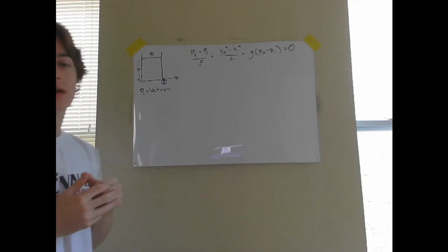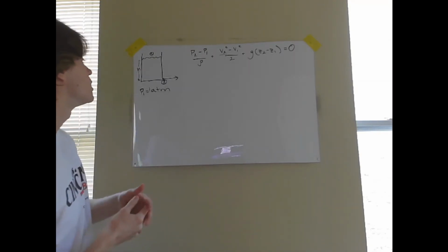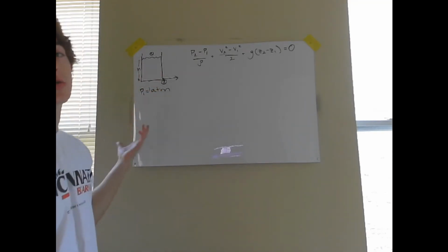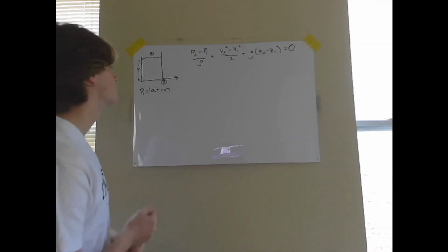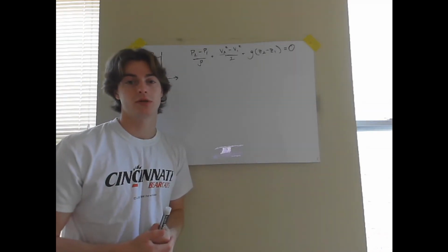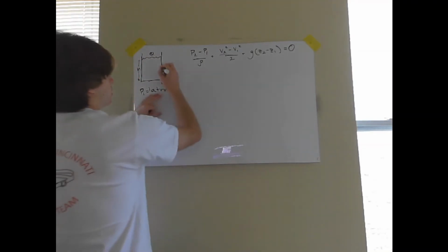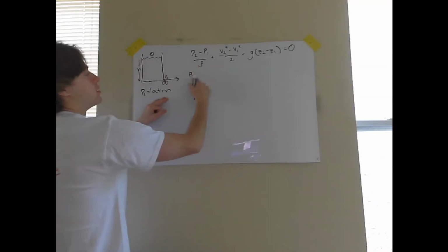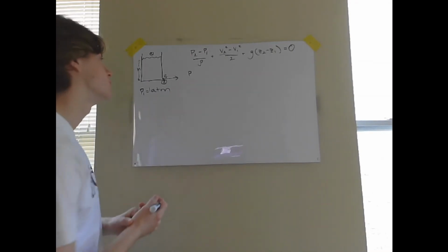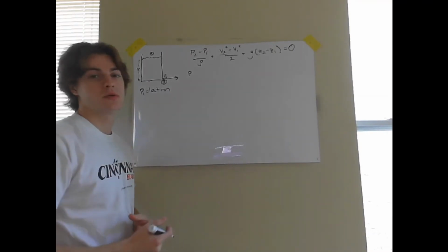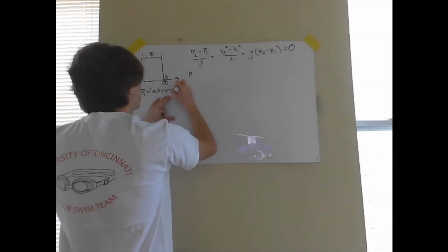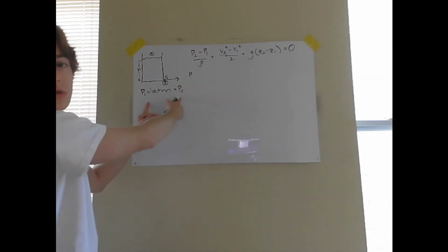Now, for the pressure at point 2, one way to think about it is we have a sudden expansion. And so the liquid rushing out of the tank goes from a very small cross-sectional area to basically a large one outside of the tank. And so when there's a sudden expansion, there's no time for pressure to recover. And so the pressure at this point, P2, is going to be equal to the pressure out here outside of the tank. And so again, since we're back out of the tank into the atmosphere, P2 is just going to be equal to atmospheric pressure. So P1 is atmospheric pressure, P2 is also atmospheric pressure. So these 2 terms are equal.